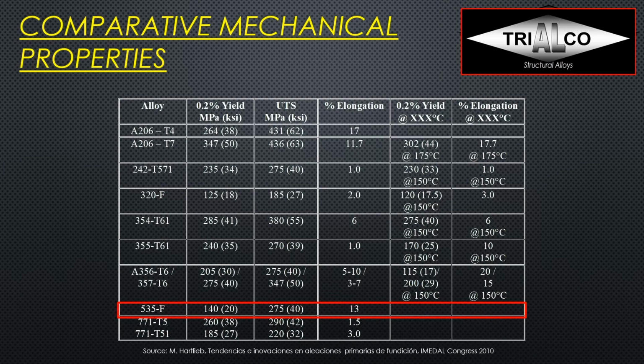Well, maybe we need really good corrosion resistance, much better than A356 is giving me, and maybe I need a certain property package where I don't need to go through a solution heat treatment process. Maybe I even want to anodize the part. Well, then I need a 500 series alloy.